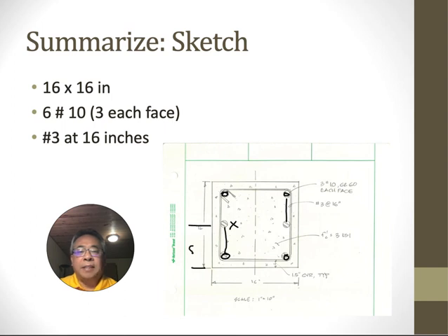That's 8. That is probably, if I had to guess, minus 2.5. That's going to be about 5.5. That's center to center. Yeah, that's going to be like 4.5 inches. So that's less than 6 inches. You're okay. If you had a really big column and that was greater than 6 inches, you have to do this. You have to put another set of bars like that. Okay, that's it. That's how you do column design.